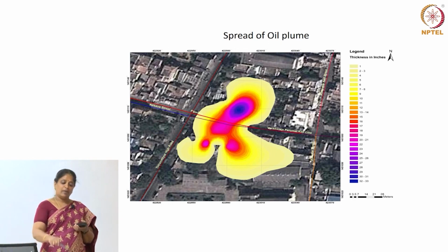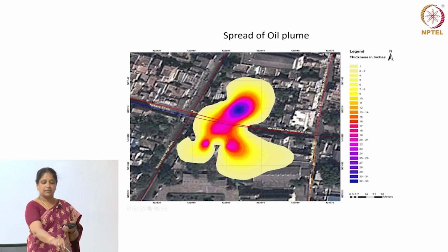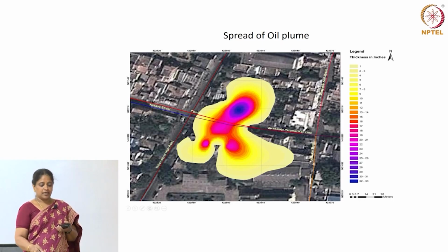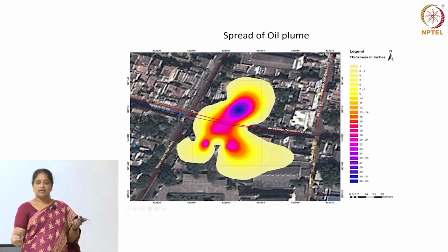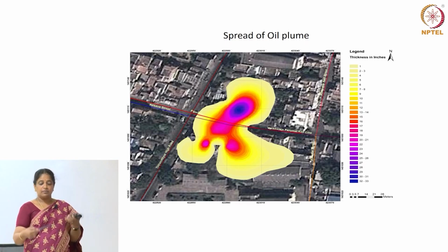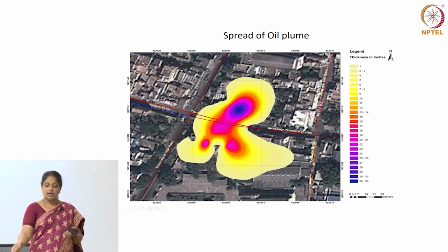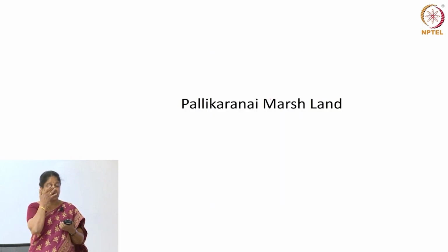And then you do multiple boreholes. We did about 25 boreholes in that particular area. These are the two major highways where the spill had occurred, and once we have the data, everything is out there. We exactly mapped what is below the ground by just doing these boreholes and sampling. We know where the oil has spread, and we also know below the groundwater what is the concentration of the different chemicals, and how far away they are.